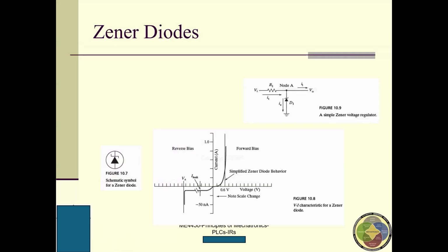It's not a constant. You can see here this is zero. The voltage here is theoretically zero, right? If I put this one in anyway, this one will be higher than zero. So this is fully reversed. Fully reversed means the diode at node A will give us a stabilized voltage. How big it is, we need to check the Zener you are using on the vendor's data sheet, and this value will be given. Questions so far? No questions?